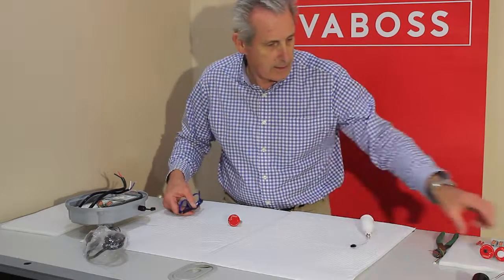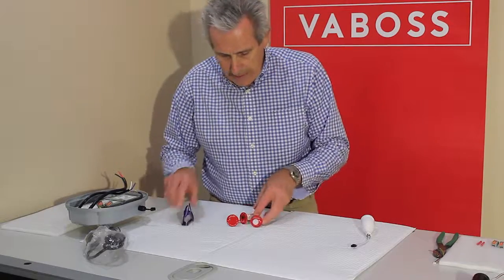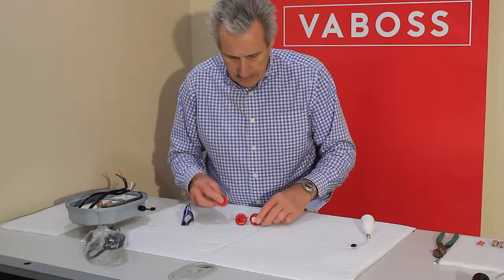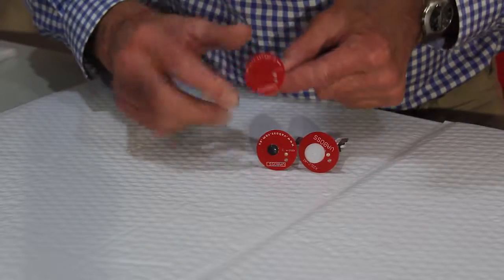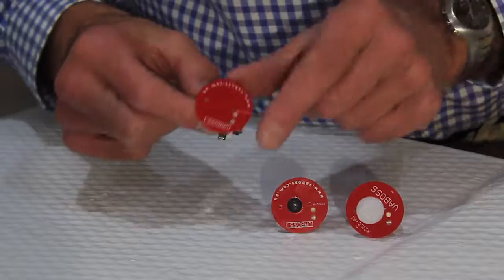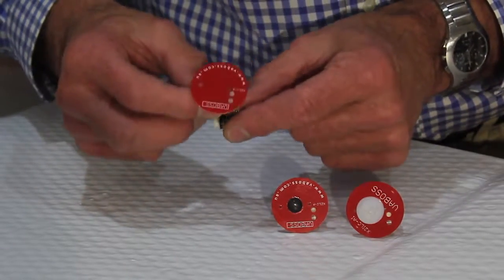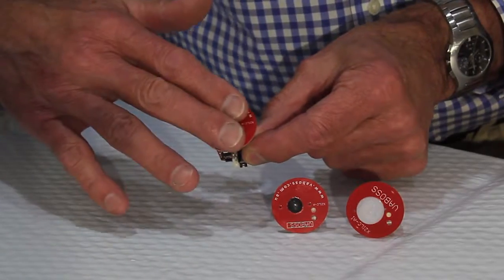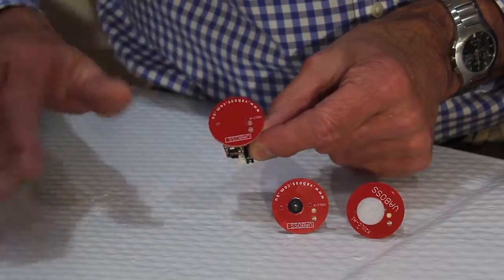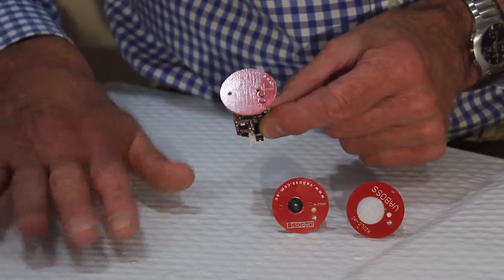Before we go on to the installation, quickly talk about the control devices. There are three basic models. The standard one, no bulb on the front. This is just ambient. This one manages light. It's called a light harvester. So if you turn the light on, this will just dim the lights up and down to maintain the same light in that spot until you turn it off.